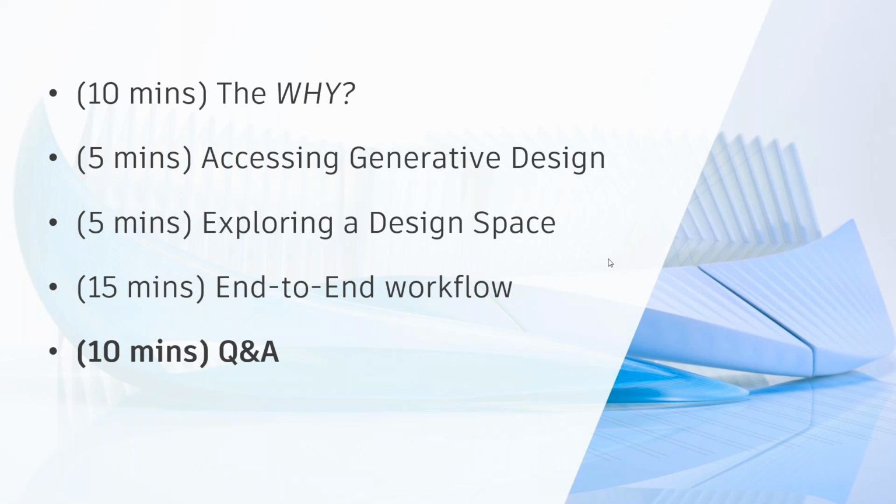So as Apollo said, the design space, the preserved geometry and the obstacle, come from the Inventor model. If I update those models, I'll get the update in Fusion 360. So the preserved geometry and the obstacle will update, but not the outcome.